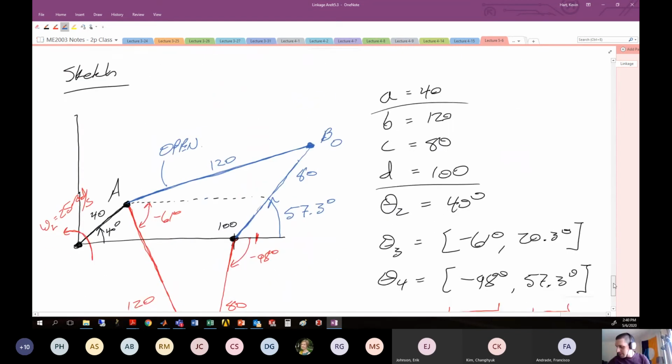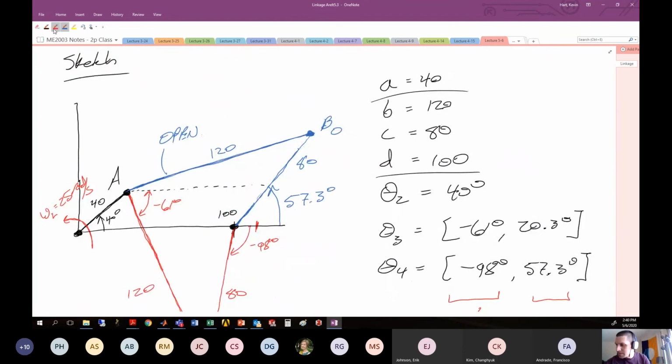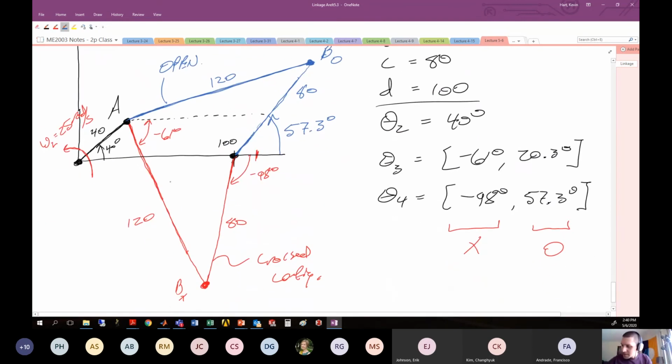What that means is at this particular point in time, in the crossed configuration, this link is moving with an angular velocity of negative 9.3 radians per second. So this guy is rotating in this general direction. That's an interesting find, that this first link is driving things, and that guy's coming down in that particular direction.